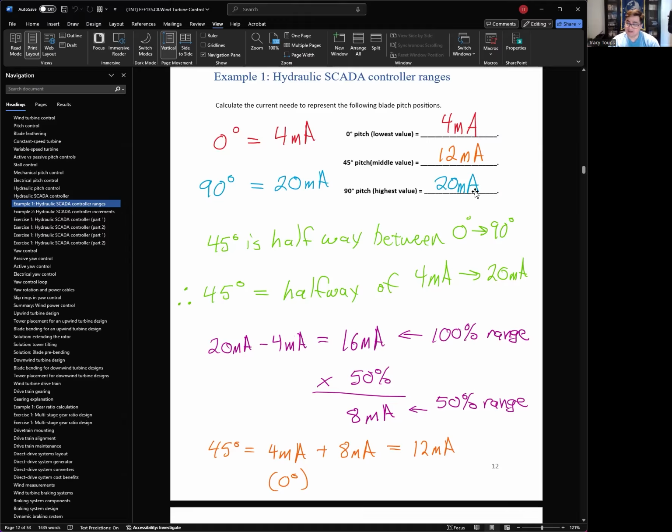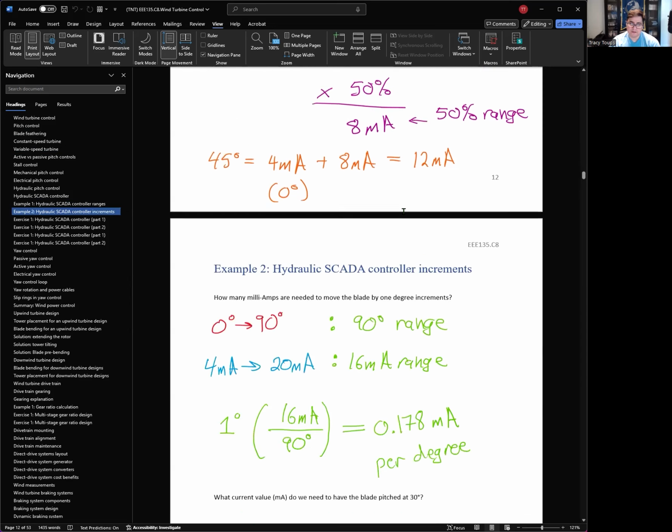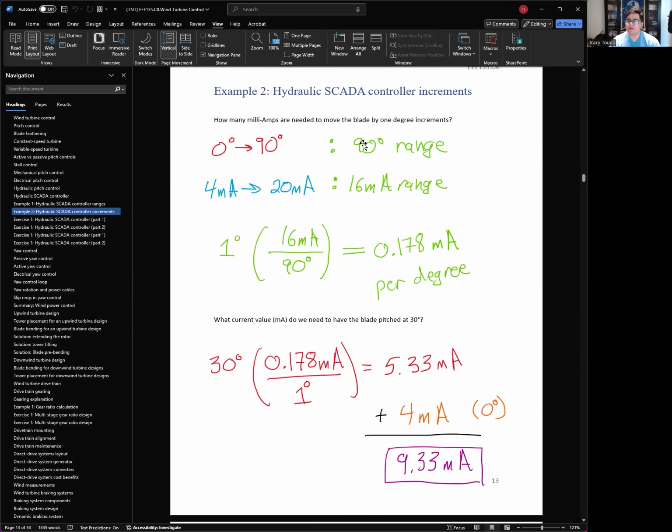All right. So it's kind of a little confusing, but you just got to remember that 0 in our case is not 0 milliamps, it's actually 4 milliamps, and you have to count up from there. So a very simple problem, but I just want to show you this range variation. And this is very typical mapping you would do. Now, let's go to the next level.